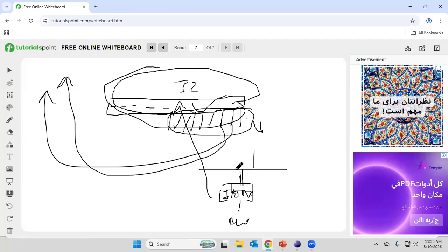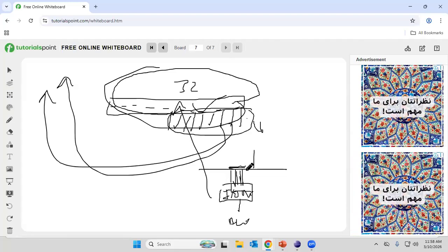It's not one line, guys. Assume that this is 16 lines here, and this is 16. So how do I transfer 32 bits over 16 lines? If there is a buffer here, it means only 16 bits can move, but the device sent 32. So the first 16 will move on the bus going to the CPU or to the RAM if we are storing in the RAM.